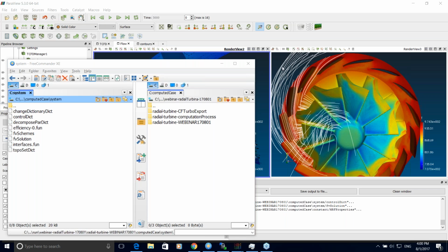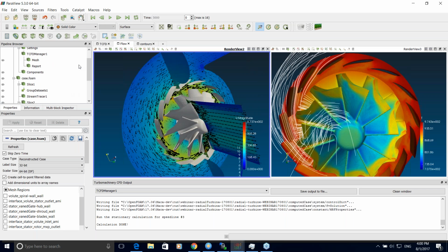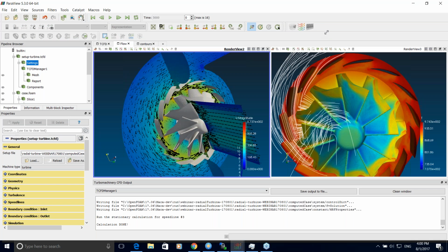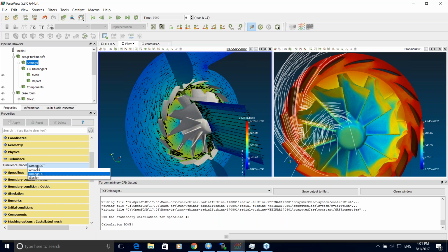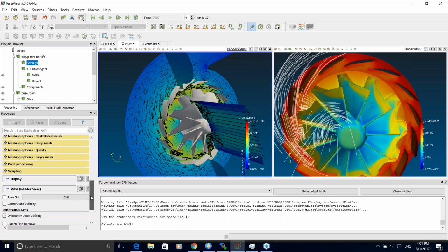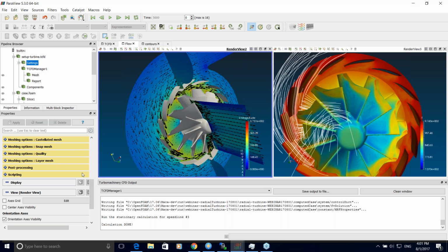Which turbulence models can be used? Radek, would you answer this? Oh yes, I can. Do you see my screen? Yes. Okay. So if I go to the setting part, by default we provide, let's say, 3 models or 2: K omega SST and K epsilon, and of course laminar, so without a turbulence model. But in general, you can use any turbulence model which is implemented in OpenFOAM, and by